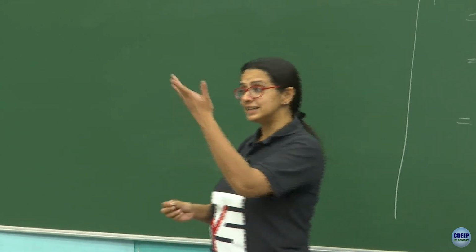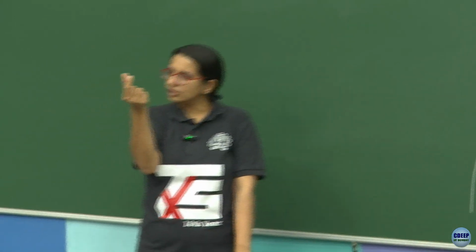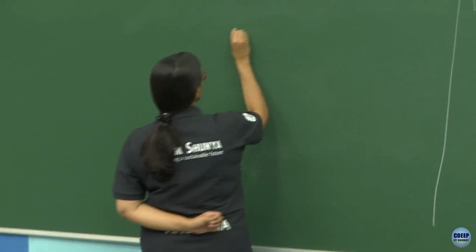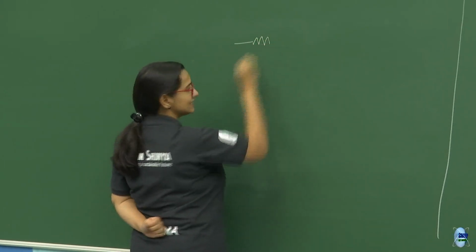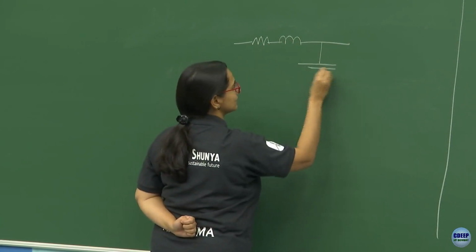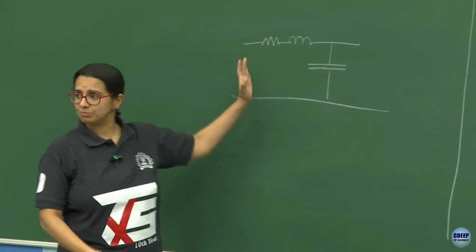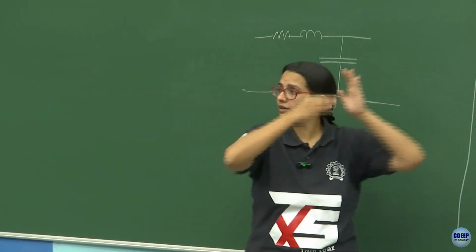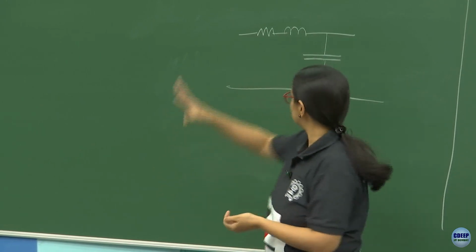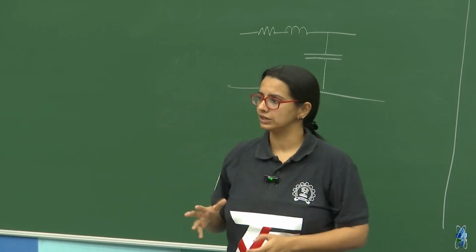Let's ignore the conductance part, but every small infinitesimal unit length of transmission line is going to have some sort of resistance, inductance, and some capacitance that's going to come into play, correct? And this block could be repeated along the length of the transmission line to represent how the electrical circuit of the line would be.